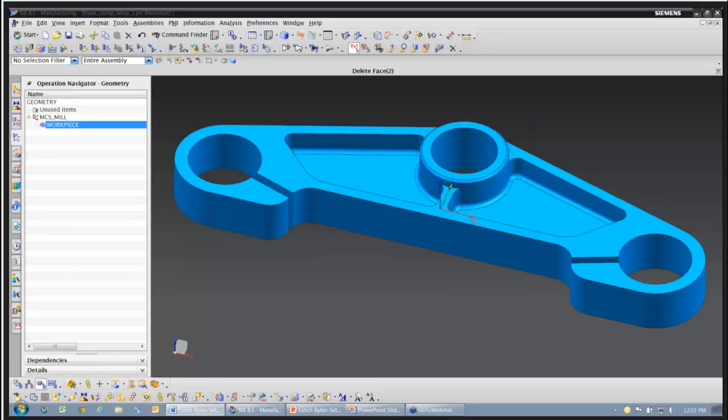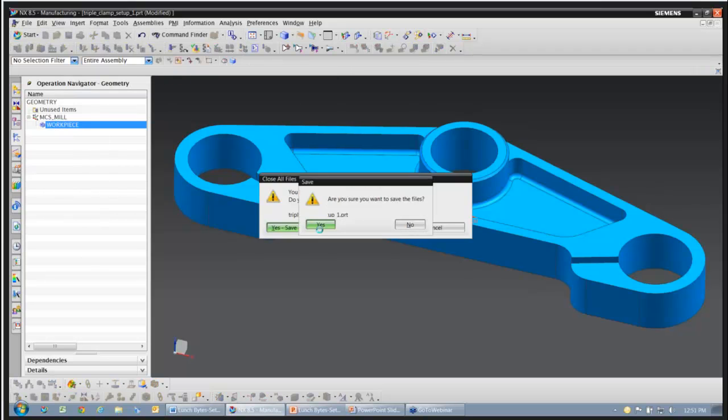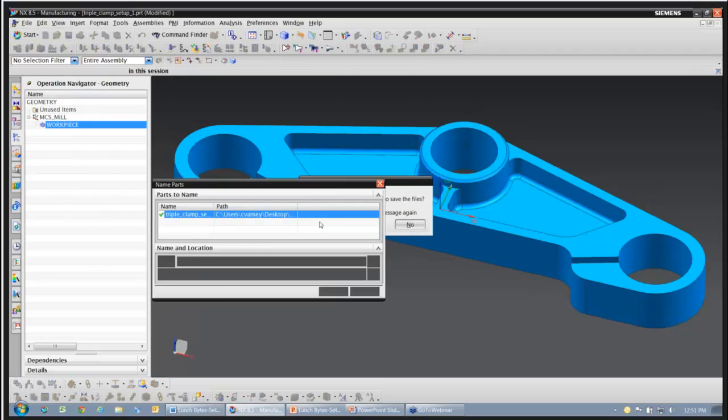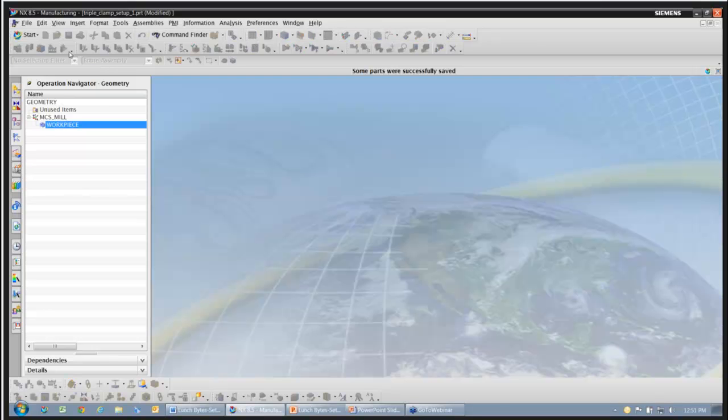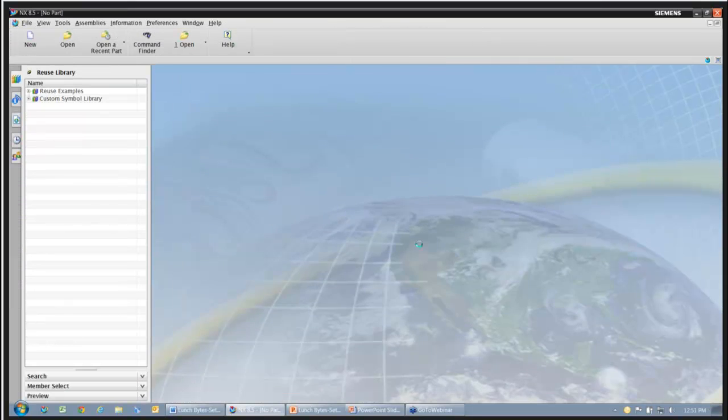I'm going to show you how we can use the original design model and quickly create another model to represent a forging using synchronous tools. Then we can use that model that we created as our blank geometry. So I'm going to close this part and open a new model. Open up this original design model. I'm going to open the original design model.